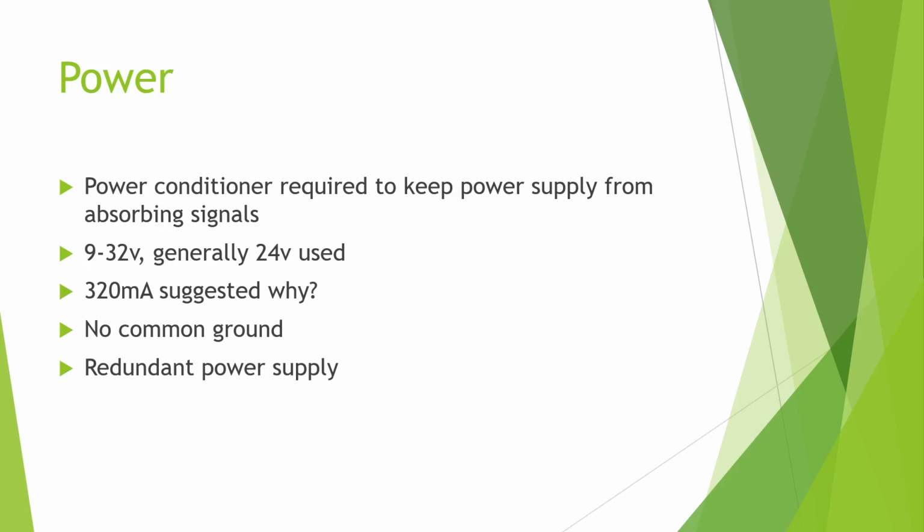So those switch mode power supplies, they're great. They're small, they're compact, and they're very energy efficient. All right. The downside is we have this high frequency pulsing happening, which, if not properly filtered and with capacitors to smooth and all those other things, is going to cause problems.